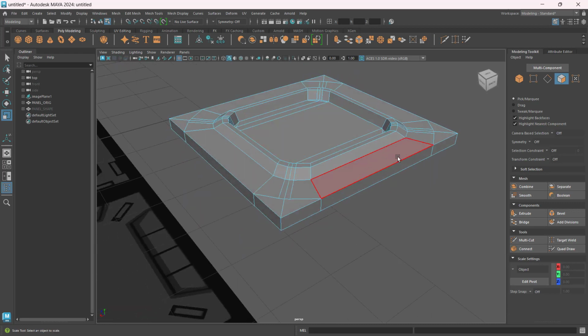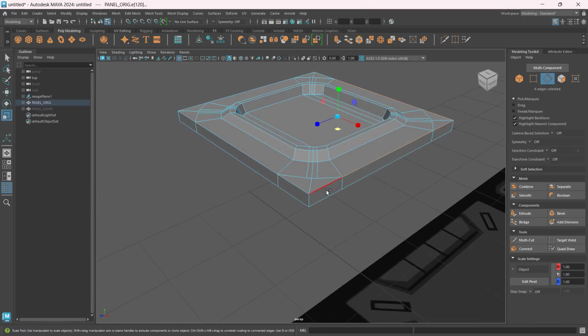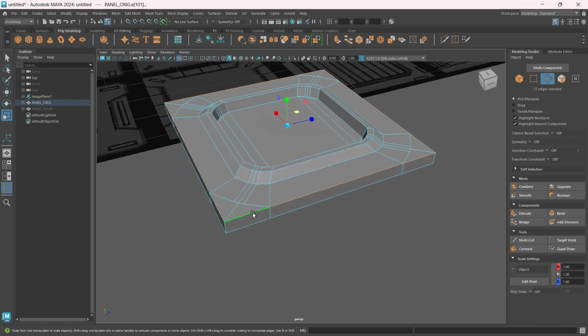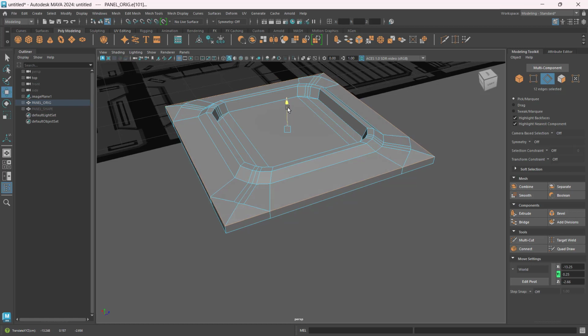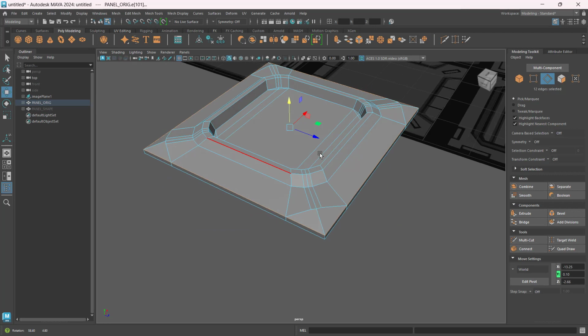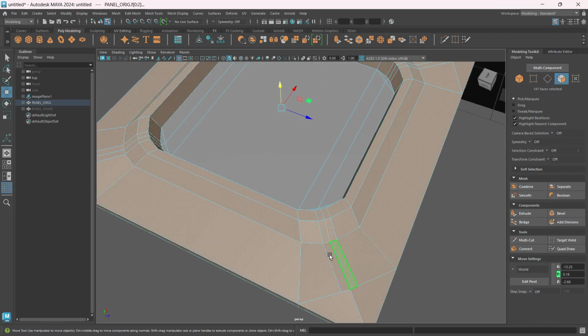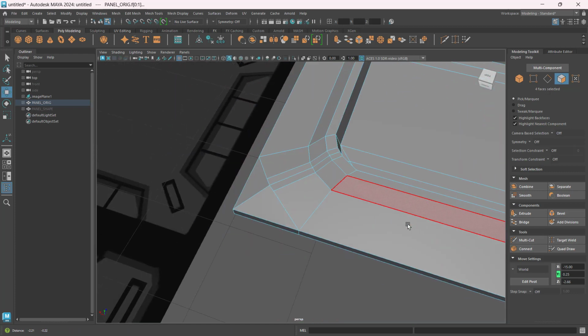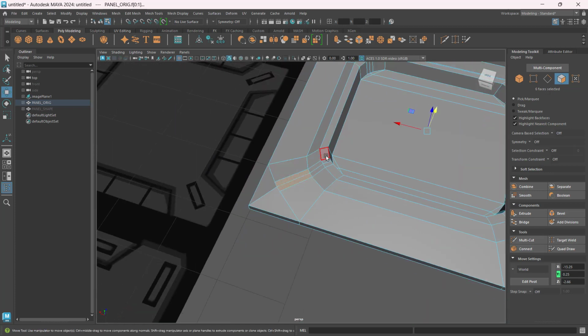So now I'm starting to 3Dify my created shape. The next thing is, for example, here I would like this to be angled. So let's say these portions here, I'm just choosing or double clicking the edges, and then W for move and drag them down. So now it is slightly angled. And then I will switch to polygon selection or face selection.